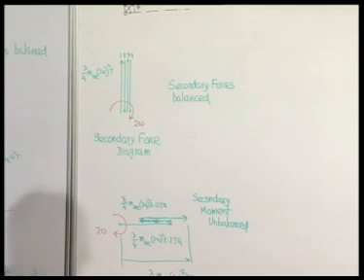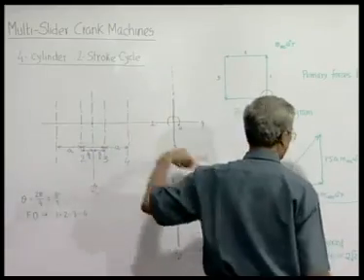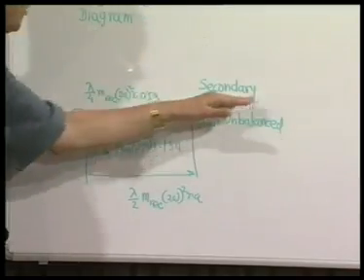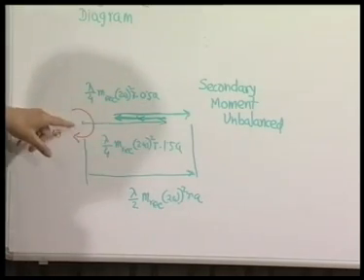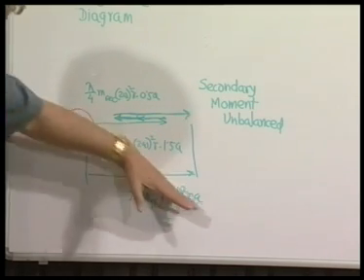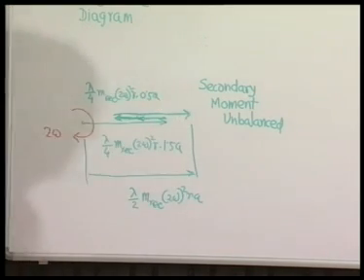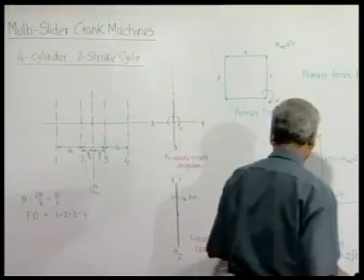And at any instant, what is the value of the magnitude? Since the forces are all in the vertical direction, their actual moment vectors will always be horizontal. So, this component is the real instant. Since it is rotating, at this particular instant we get the full value, but at some other instant it will be inclined and we have to take only the component. But the magnitude is given by the maximum value as it was done here.